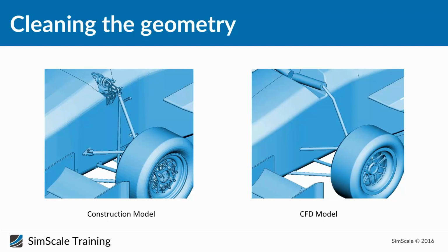Next question is by David, but was also asked by Eva Maria and Shivansh. It's about basically which formats you can use. Guys, as you know, on SimScale, you can upload IGES, STEP files, as well as STL files. Nevertheless, we strictly recommend to upload STL files only. The reason is the meshing tool we are using, SnappyHexMesh, only accepts STL files as an input.